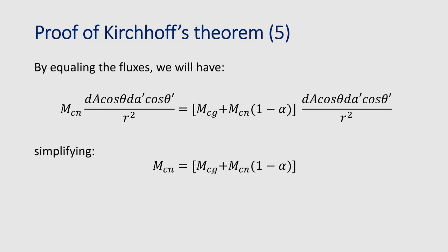Whenever I compare these two surfaces with each other inside the radiant cavity, the equalization of the flux will be the same. So this demonstration of Kirchhoff's theorem is independent of the mutual position of these two infinitesimal surfaces inside the radiant cavity.